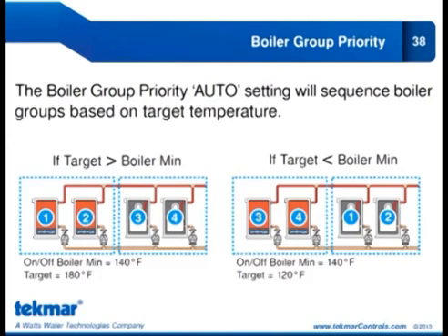Now, the question is, when would this come up? When would you have an application with both condensing and non-condensing boilers? Well, it might be a retrofit. Maybe it's new construction. They want to save some money, so they put in, say, a Category 4 non-condensing boiler, which can achieve 87-plus efficiency, and they combine it with some condensing boilers. So they can save significant capital costs.